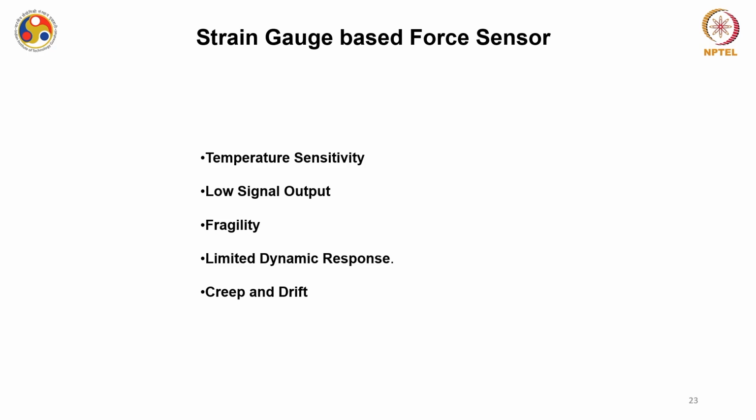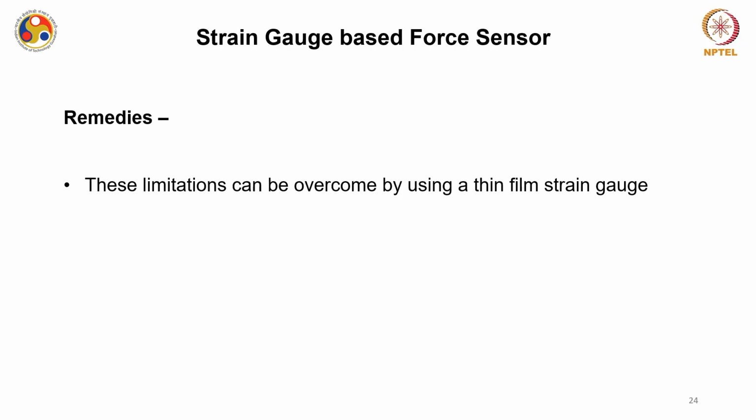And the creep and drift of this device is very important to be considered while you are using it for measuring micro forces, or say nano-Newton kind of forces. Okay. There can be various remedies. These limitations are mostly overcome by using thin film based strain gauges.